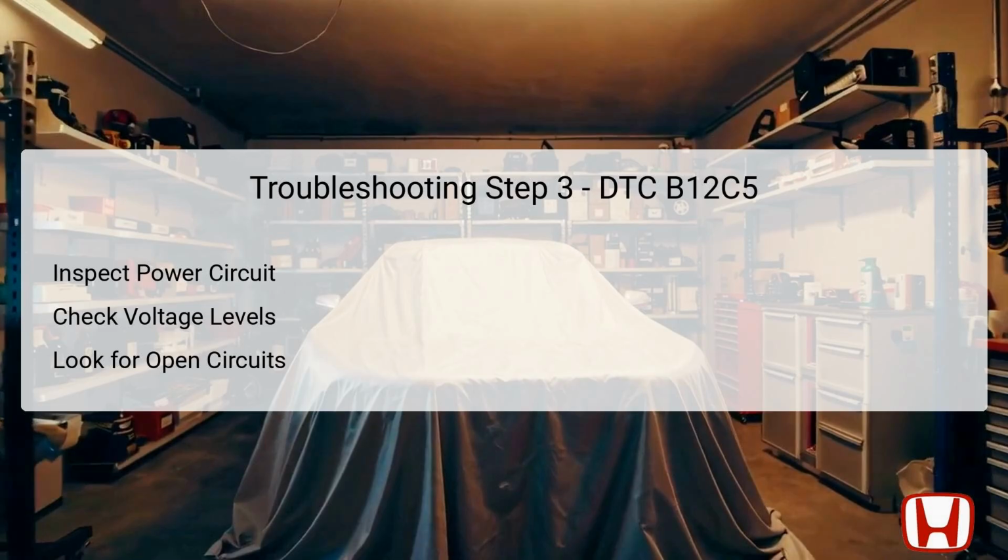This involves checking the voltage levels in the positive smart power supply circuit, plus B Smart, and ensuring it is delivering the appropriate 12 volts under normal conditions. If the voltage levels are not within expected ranges, it may indicate issues with power delivery to the switch or the body control module. Additionally, you will want to look for open circuits in the external connections.